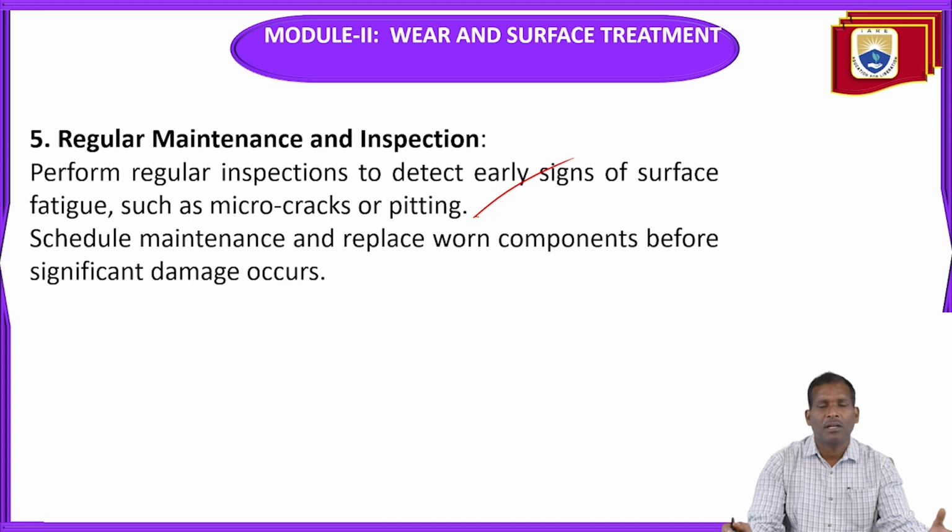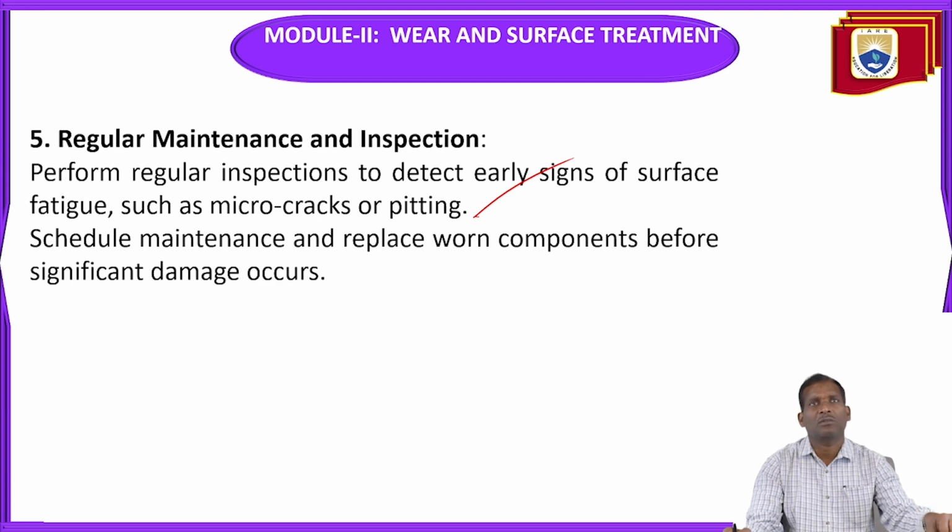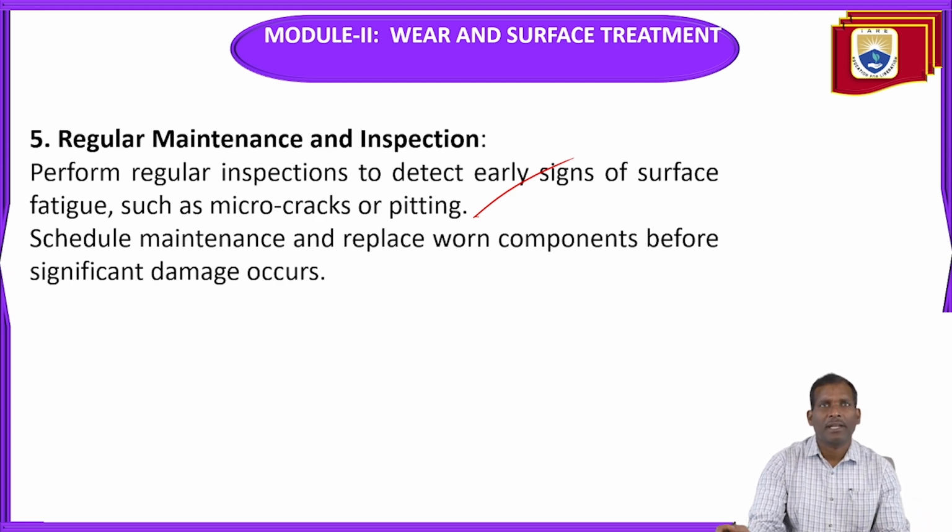Whenever you observe some small cracks or pitting, you need to do maintenance immediately and conduct frequent inspections. By doing this, you can minimize the surface fatigue wear.